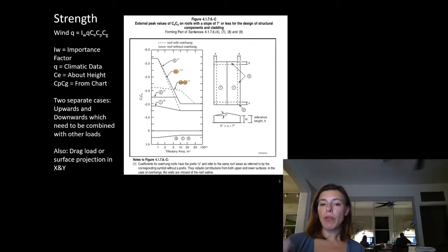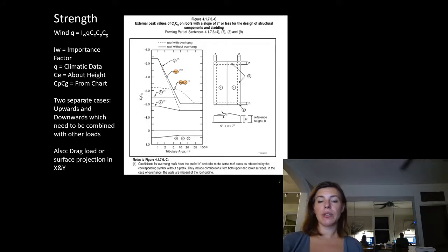And it's still only 0.4 as a companion load for wind, but if wind is the principal load of 1.4 and we have wind and we have snow, the snow needs to be 1. So that can really increase the amount of load our elements are seeing.